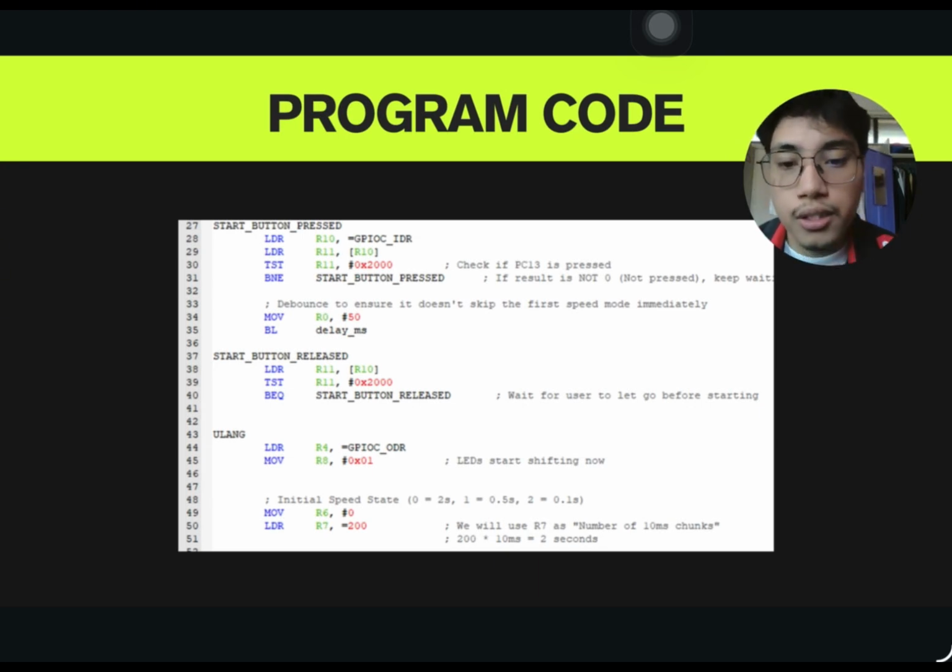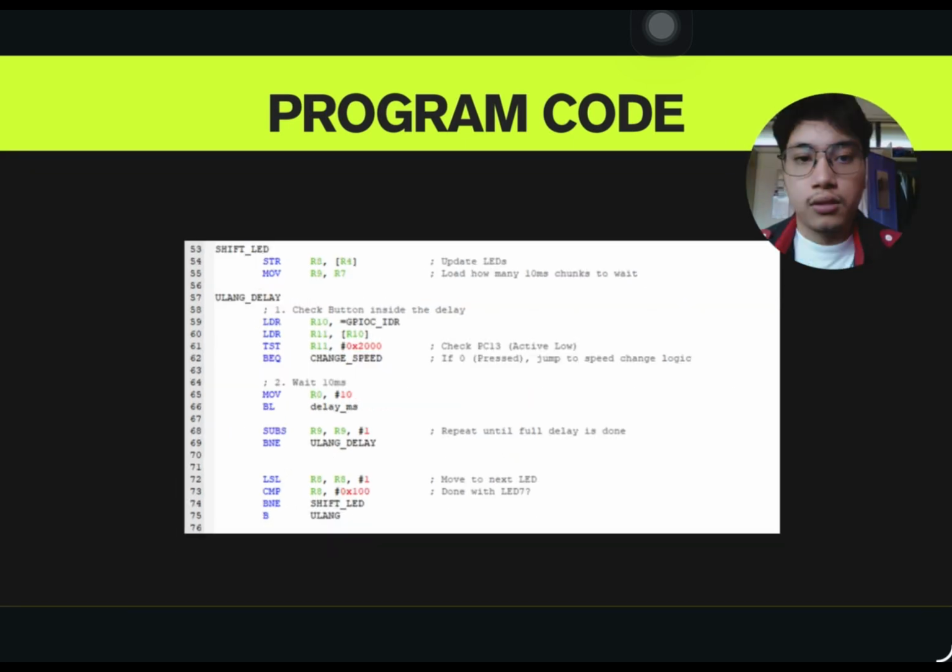As we can see here, initially the value of R6 is 0. So the initial speed state and the delay from one LED to another LED is 2 seconds. R7 is the value of delay. One chunk is 10 milliseconds, so 200 will equal 2 seconds for each.